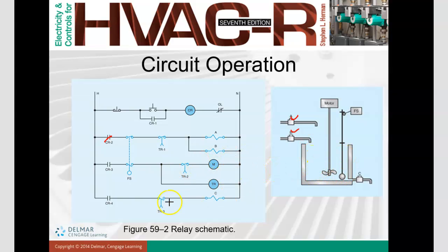Okay, until this float sensor reaches the level, I mean this one also reaches the level. Okay, this float sensor will go up, and then what happened? This is normally closed, become open. That means A and B will not have any power. So it will cut off. Okay, and then line number 3.